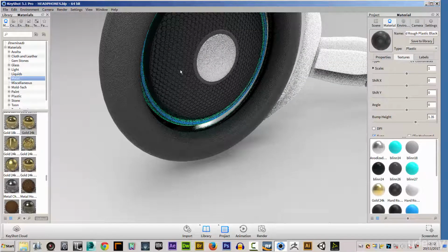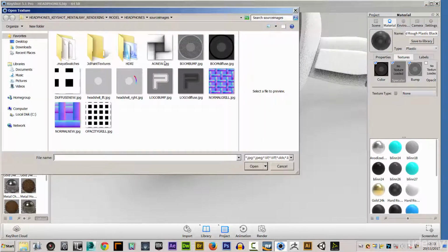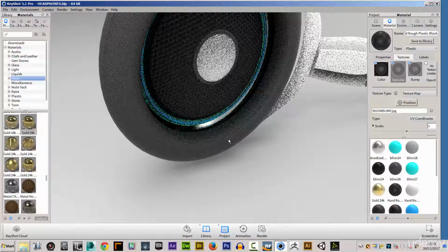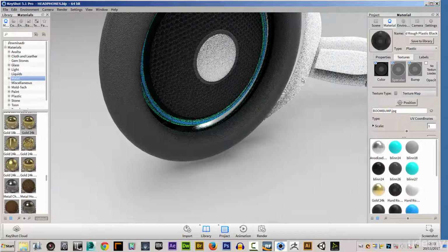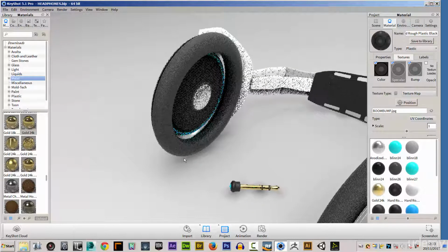And finally, where we've got the specular, I'm going to come into the textures and use the bump as the specular. And there we go. So now, because it's on the hexagons, it's lighter. It's going to pick up the light, but inside it's darker, so it's going to pick up less light. It's very subtle with this, but it should look quite good.